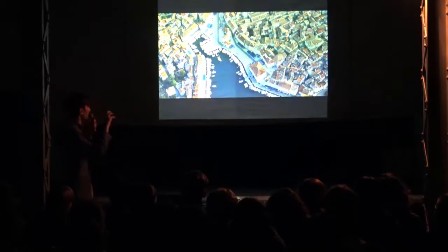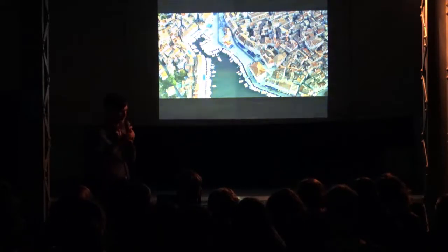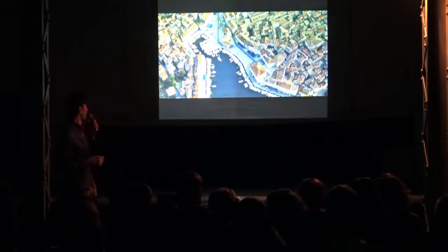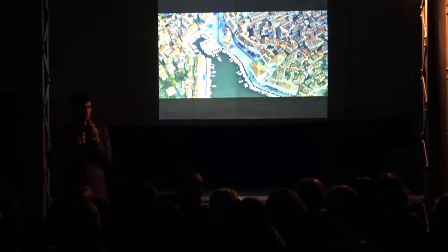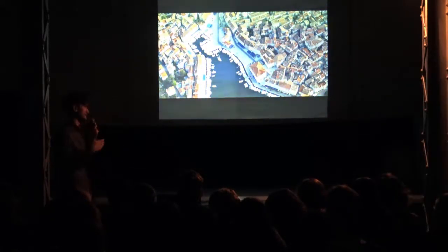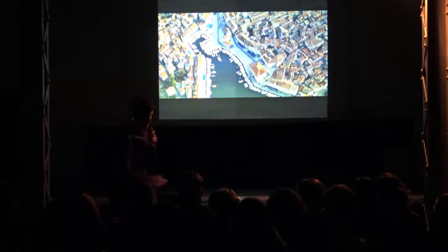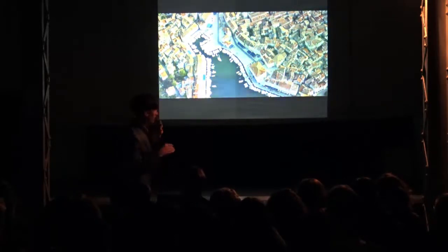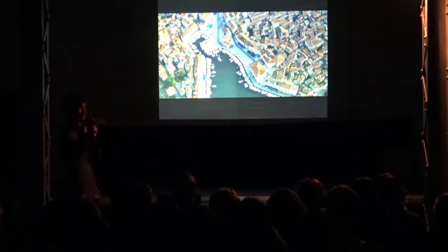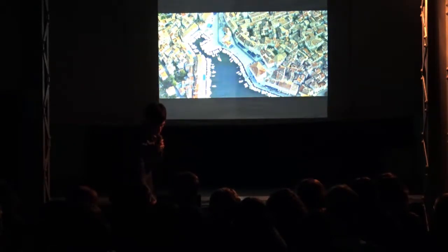So you have these very small buildings nested closely to each other, typical for the whole Mediterranean. Basically, the reason why they were building it like this is due to the weather, right? In the summer, you have a lot of heat, so the thick walls and small windows prevent the heat going inside the buildings. While in the winter, when there are strong winds, the meandering, labyrinth type of streets prevent the wind going through the city, through the urban matrix.